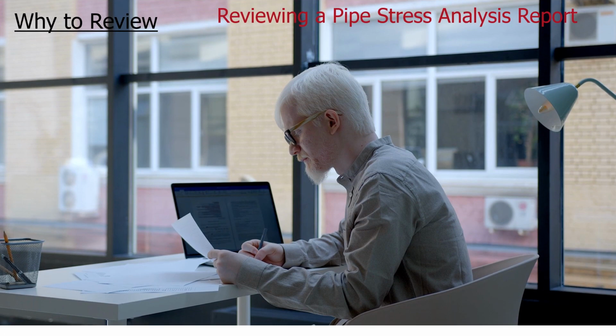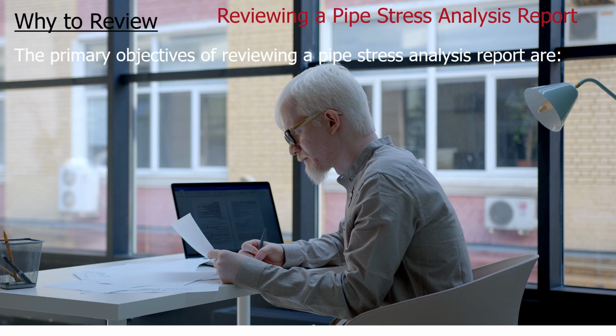Now, why to review? What are the main reasons that a stress analysis report must be reviewed? The primary objectives of reviewing a pipe stress analysis report are: first is verification of design. We know that a stress analysis report, whether it is piping or pipeline, must be designed based on some design codes. For example, process piping is designed based on ASME B31.3 code.